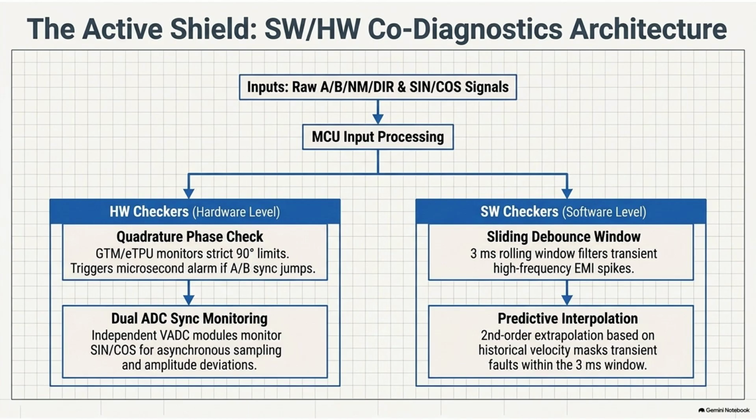So basically, the doer is navigating based on the GPS, the physical encoder. Right. And the checker is sitting in the passenger side, completely ignoring the GPS and calculating their exact position based purely on the physics of magnetic flux conservation and back EMF. That's a great way to picture it. And the system constantly compares the encoder's reported angle against the checker's mathematically predicted angle. And the specification notes that if those two angles deviate by more than a calibrated limit, specifically greater than 10 degrees, it means the encoder data is fundamentally flawed. Yes, and when that deviation occurs, the safety core bypasses the main control software entirely and triggers a hard shutoff in under 100 microseconds. Wow.